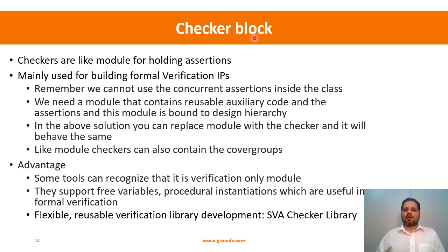So the checker block is again a new container that has been introduced in, I think, the 2017 LRM. Checkers are like a module, again similar to a program block. A checker is a module equivalent for holding assertions. Okay, it's mainly used in building formal verification IP. So the way we have simulation verification IPs for each of the protocols and for many other things.